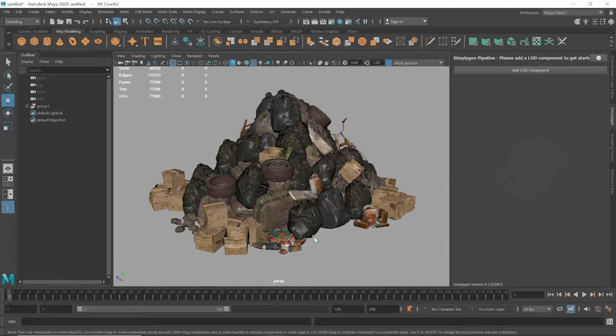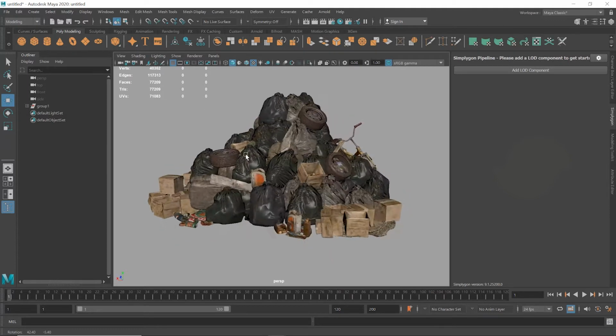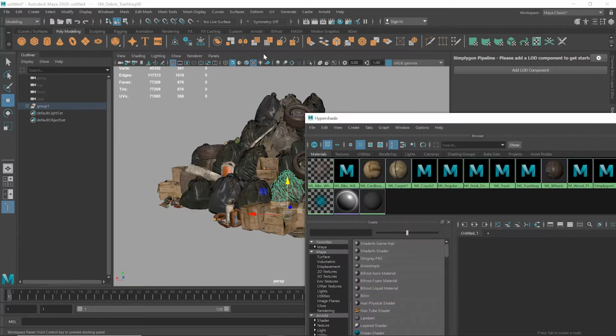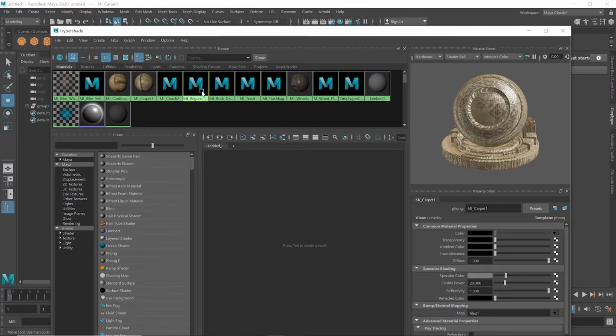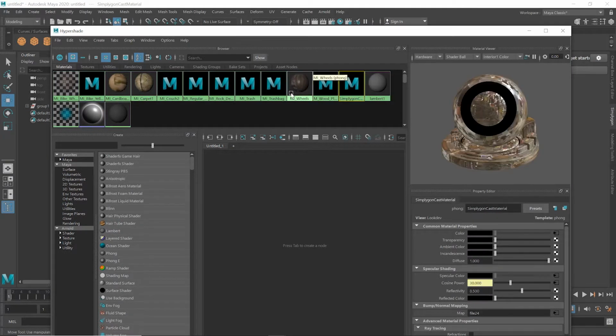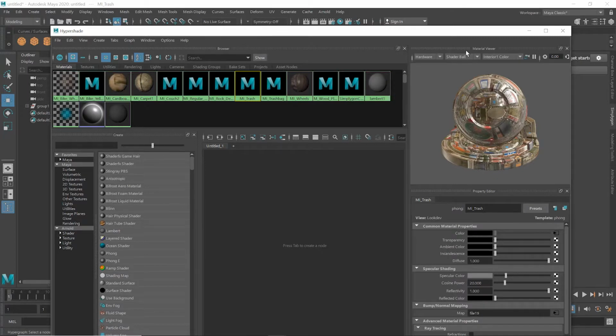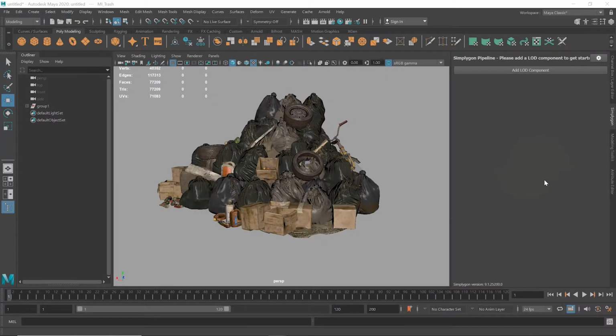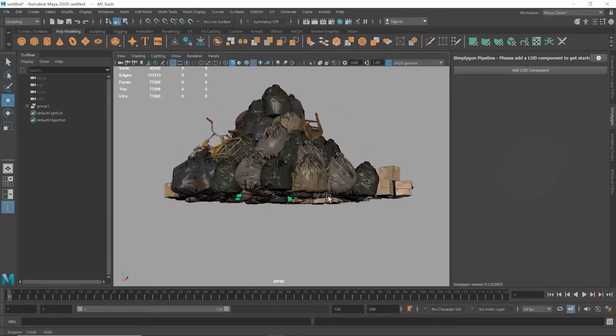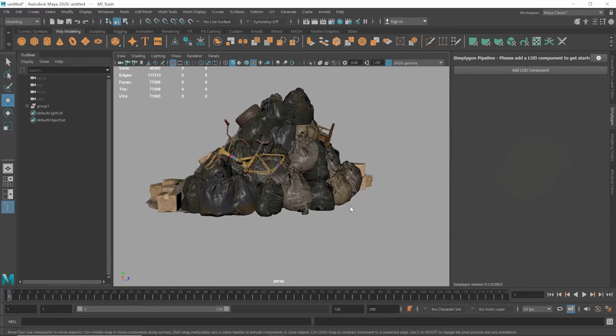Aggregation is a Simplygon optimization method used to transform a group of many objects with many materials into a single merged object with a single material. With this method you can keep the original UVs, meaning that areas sharing the same texture space can be preserved. This is important when merging kit-bashed object collections where there tend to be many objects sharing materials. Casting the materials for these kinds of object collections would lead to texture duplication, a blurrier texture at the same resolution. With aggregation, the texture space in the combined material will be more efficiently used, allowing us to view the merged object as closely as we would the original group of objects, while reducing the draw call cost.